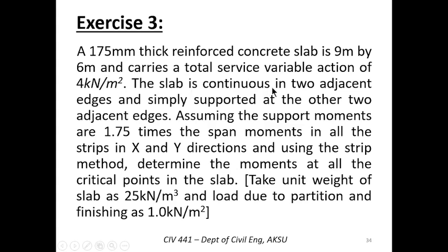The slab is continuous on two adjacent edges and simply supported at the other two adjacent edges. Assuming the support moments are 1.75 times the span moment in all the strips in x and y directions, and using the strip method, determine the moments at all the critical points in the slab.